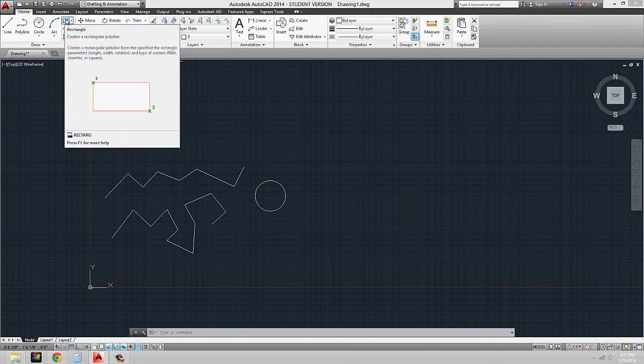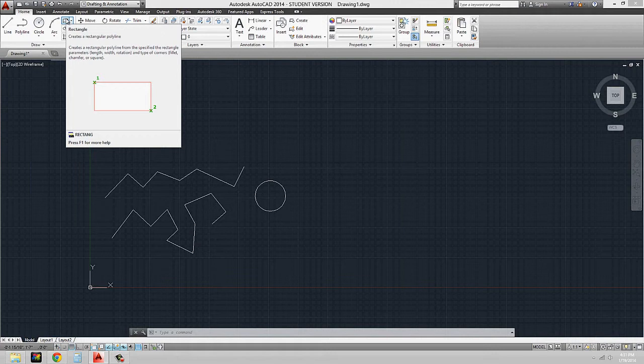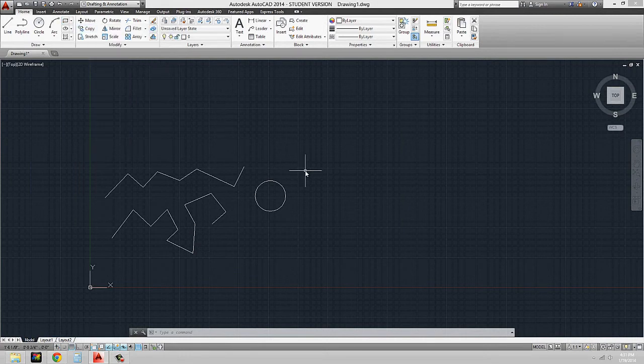And you can either type in REC or RECTANG, okay? Again, you'll notice when I mouse over there, at the bottom of that window, it shows you the rectangle, okay? And that's the command for rectangle. So rectangle, what I can do is I can just type in the command, okay, specify first corner and another corner. And we'll see another way of entering dimensions into the rectangle as we go through and start to specify specific types of